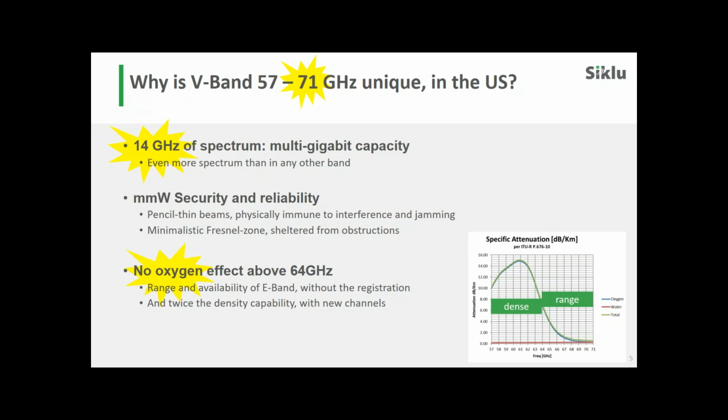So you basically have the option to configure ETH2 and ETH3 on the radio to do 26 watts power out of ETH2 and 3, or you can change the balance to 46 and 13, and you can even go all the way to 52 watts on ETH2 and nothing at all on ETH3. In case you have maybe a small cell that somebody would like to deploy, or maybe a PTZ camera, you have 52 watts, which is a good amount of power for many different applications.